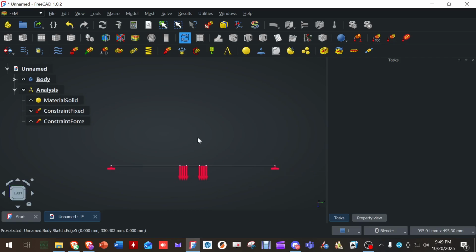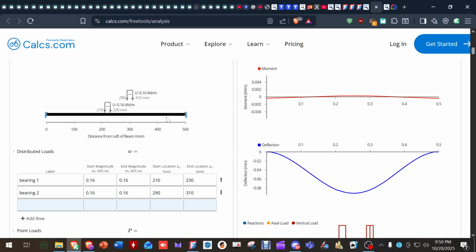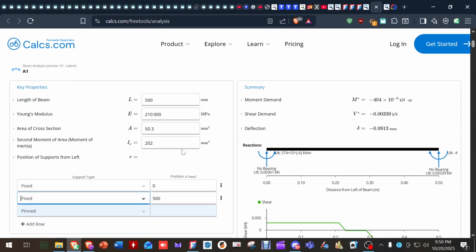The last thing, actually there's two things we need to do. So the second to last thing is we need to add some sort of 1D geometry cross section, because in order to do any type of beam calculation, it needs a cross section. Notice in here it needed an area cross section, so we're going to add the same thing to here.